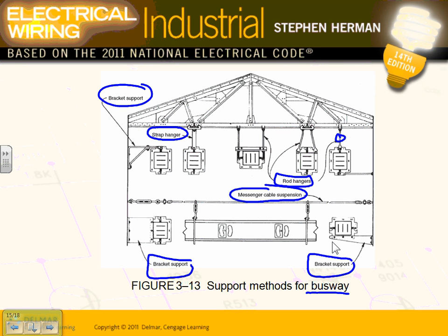If you look at the left-hand side of that page, busway or bus duct, can you see the single phase and 3-phase? Ignore the single phase. Always look at the 3-phase. You can't buy smaller than 225 amp. Well, you can if you custom design it. So the smallest plug-in busway you're dealing with is 225 amp.